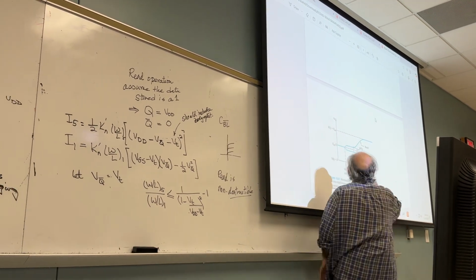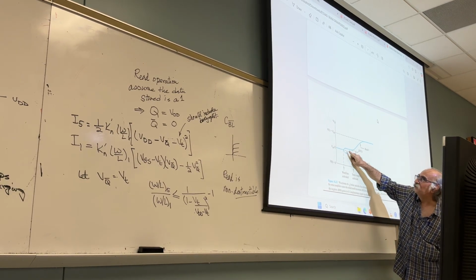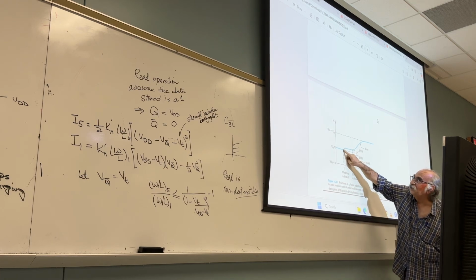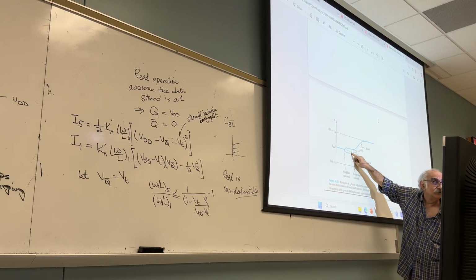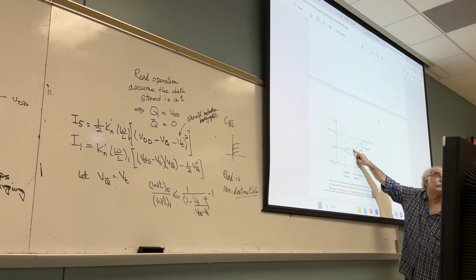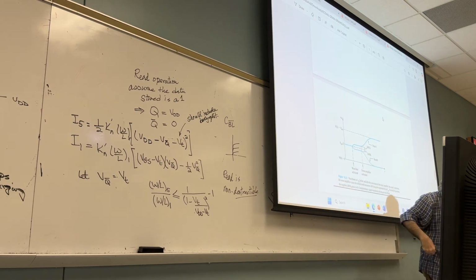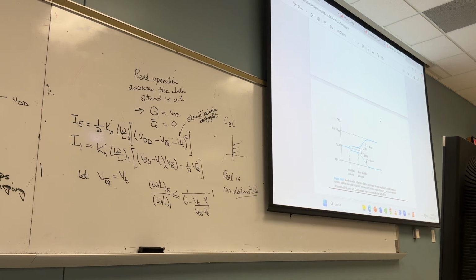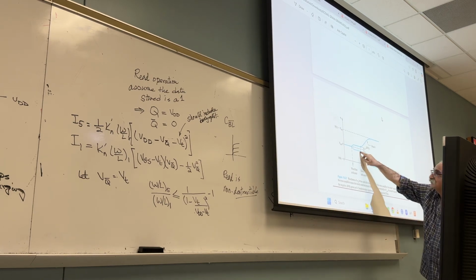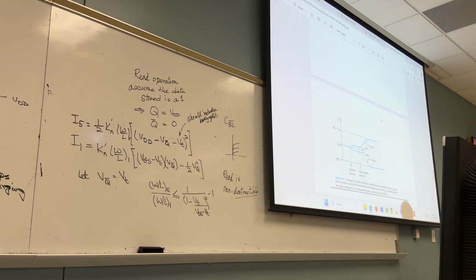At this point, what happened? The sensor sent increase rather than decrease. Did you get it or not? If he sends increase, what does he do? He jumps to VDD. Which means he declared that what is being stored is a 1. If it decreases, he goes to 0. Declare that what is being stored is a 0. Did you get it? Yes or no?